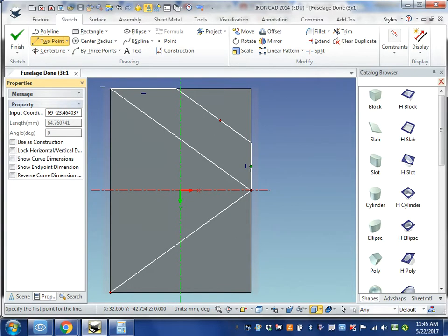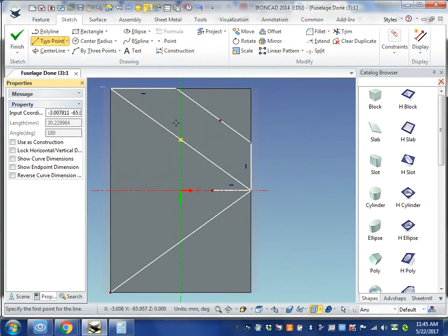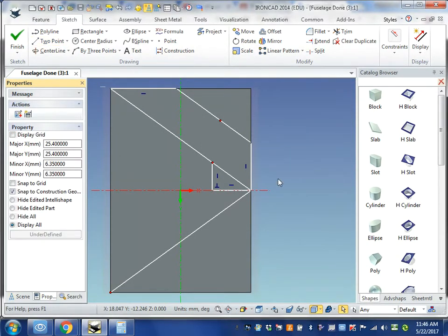And we're going to make this 38 right here. So I'm going to do a 2-point line right here, dragging forward. I'm going to come forward. I'm going to enter 38 and press enter. And I'm going to do a 2-point line. I am right clicking here. I'm going to intersect right there. I guess I didn't need to right click, but clicking right here and right. Actually, I'm going to hit escape. We'll use the mirror to fill this in. Let's use the mirror command. Rather than recreate everything on the other side, we'll mirror what we want.